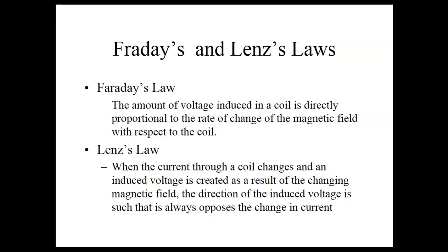So this is what's happening, we've got these things coiled together. When I put current flow through this one, it comes out like this. But there's another coil right beside it. So it's coming out of this one, and it's going to cut the wire right beside it. If it's going this way in this one, it's going to try to induce a voltage going that way, which is going to try to oppose the voltage in the coil beside it.